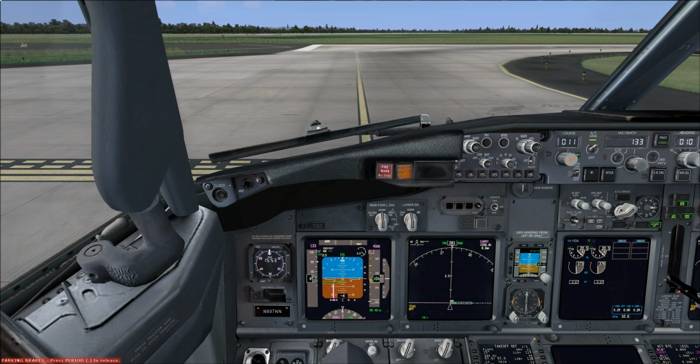Now, what will happen is, if you're on approach to landing, the first thing you'll get is an increase in airspeed. And with that comes, naturally, an increase in lift, which if the pilot isn't aware of what is happening, he'll try to correct for it by lowering the nose and reducing the engine power, because that increase in lift causes him to get above the glide path, and then as he flies into the increased headwind, he'll get into the downdraft.